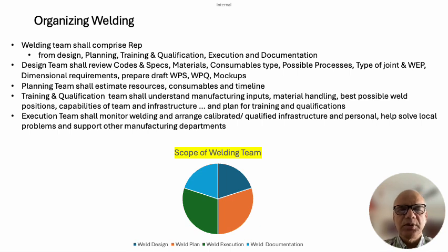subsystems in which we'll be executing the fabrication and then doing the final welding to have a full sub-assembly or equipment. All those discussions are done, the codes and standards are referred, understood. If there are any heat treatments required, if there are any special precautions which are required to be taken on the reinforcement, on the penetration, if these joints are going to become single-sided because of certain fabrication requirements.